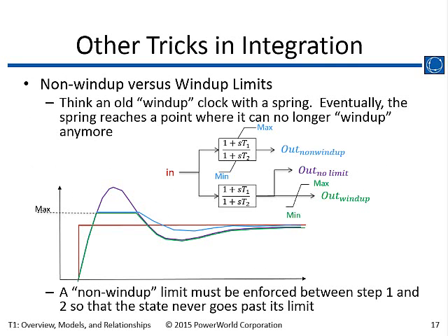There are tricks in dealing with integration. We'll get into block diagrams a little bit later on. I was very unfamiliar with block diagrams until I started doing transient stability development in 2006. Since then, I've gotten quite familiar with them. When you do block diagrams, this might be on an exciter or a stabilizer. You get a signal coming in, and in this case it goes through a lead-lag block. The details here don't matter. The point is, a lot of times those have limits on them. How the limits are enforced is important.